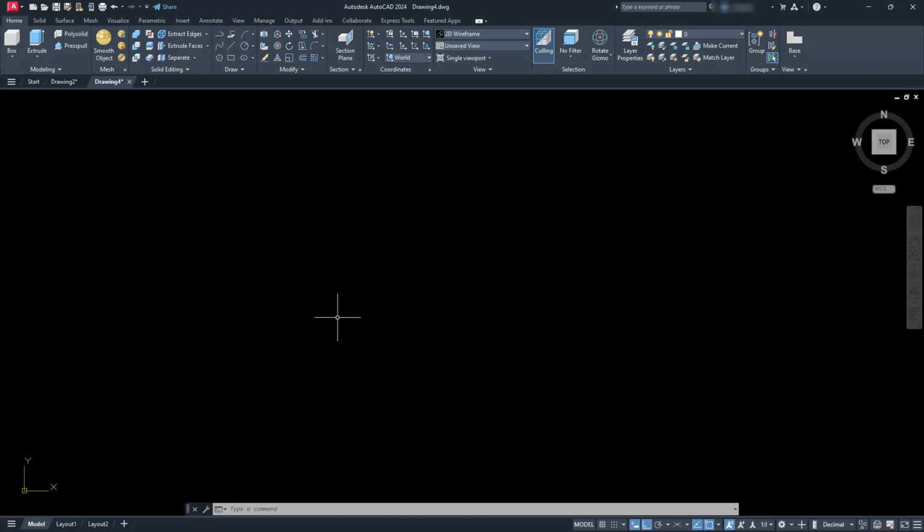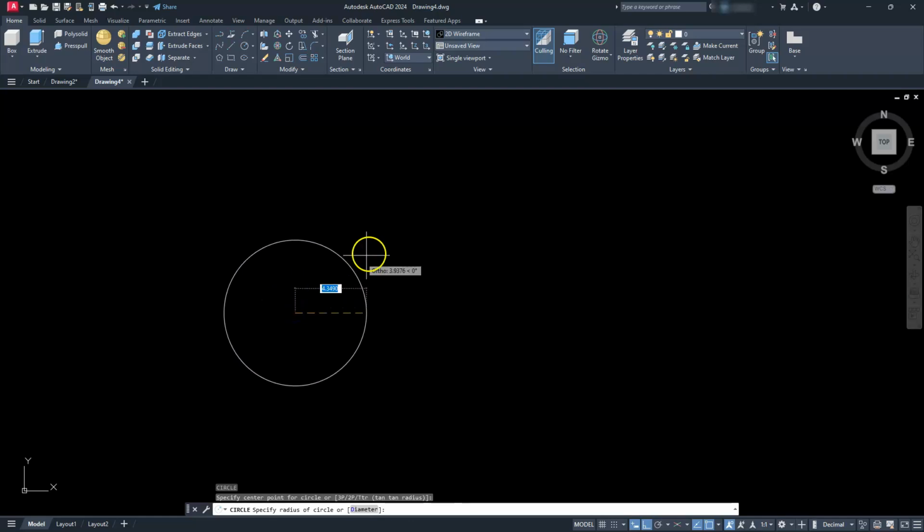So I'm going to first start off by creating a circle with a radius, right? And I'm going to do this just typing in the keys, and I'm purposely doing this because it is going to speed up your keystroke. So if I just type in C, enter, and that just stands for circle, I'll click here, start previewing my circle, and then type in 15.